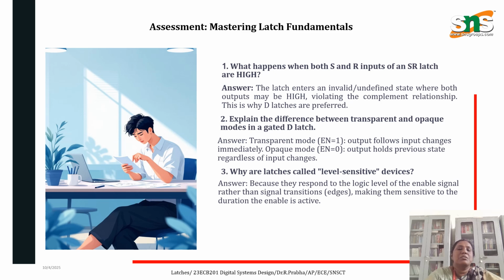Third question: why are latches called level sensitive devices? Because latches respond to the logic level of the enable signal rather than the edge transition, positive edge or negative edge.